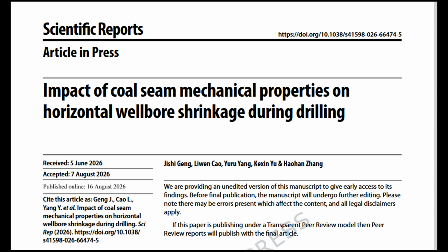Equation 1 states the Mohr-Coulomb yield condition for the plastic zone around the wellbore. In plain words, it says that yielding occurs when the tangential hoop stress around the hole exceeds the radial stress by an amount that depends on the material's internal friction angle and cohesion. The larger the friction angle and cohesion, the higher the stress difference the coal can withstand before it flows plastically.